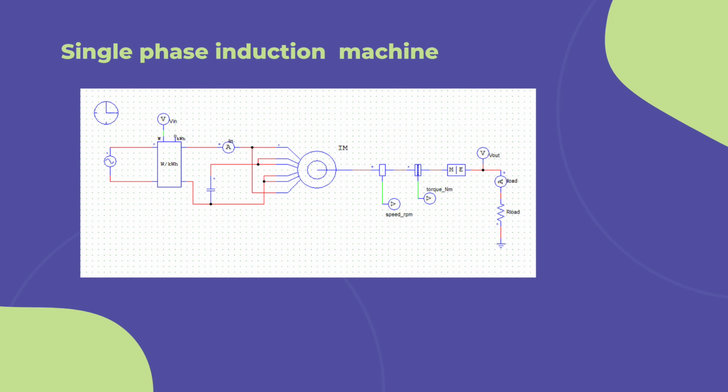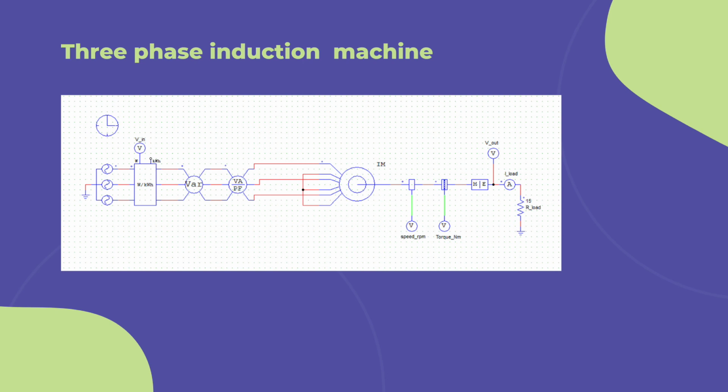Then set the initial capacitor value to 400 microfarad and the input terminal voltage to 240 volt. Run the simulation and we repeat the same step using different values of capacitor from 400 microfarad until 40 microfarad. After varying the value of capacitor, then we vary the value of input terminal voltage from 200 volt until 240 volt.